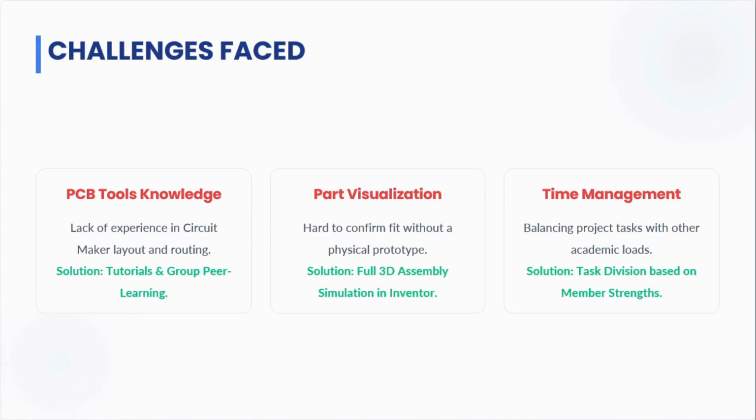Once the schematic was verified, we moved into the PCB design phase. The layout was prepared using CircuitMaker, and we made sure to strictly follow standard engineering design rules throughout the process. First, we optimized all our trace lengths. Keeping traces direct is vital for maintaining signal integrity across the board.